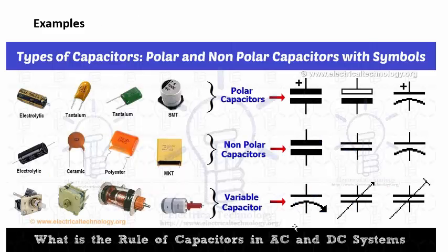So here are some examples of capacitors and also what their schematic symbol is. These are polarized capacitors shown in the top row. Electrolytics, which will have the minus sign marked on the side as so. Tantalum, which I have many examples of in the lab that you can look at. And there is even a larger surface mount capacitor package for electrolytics.